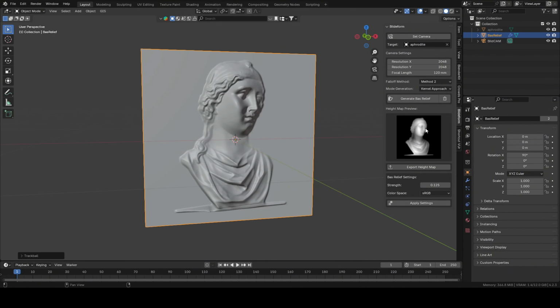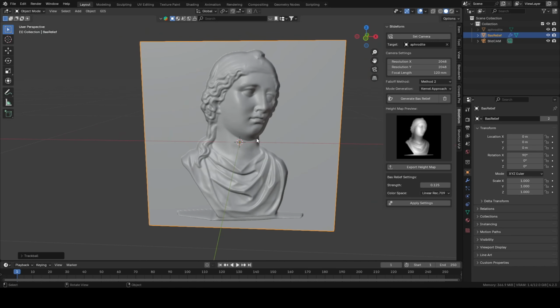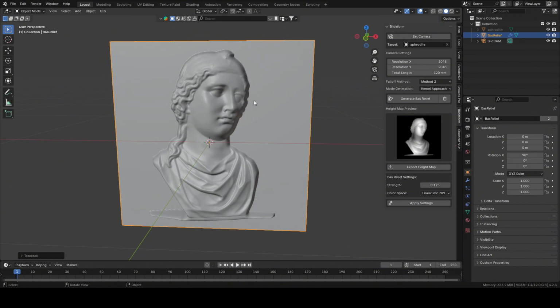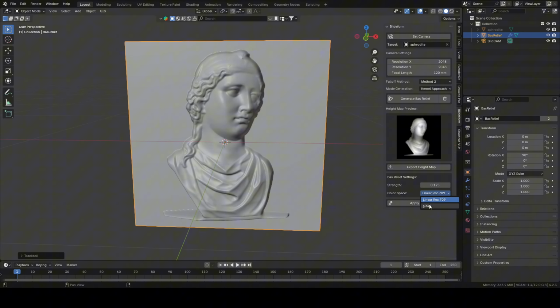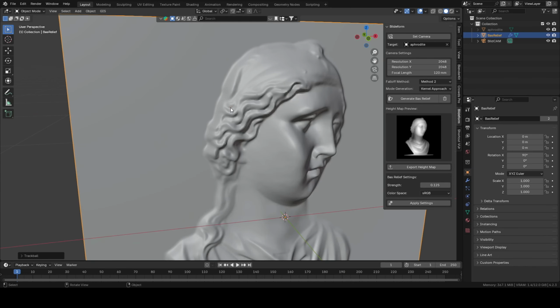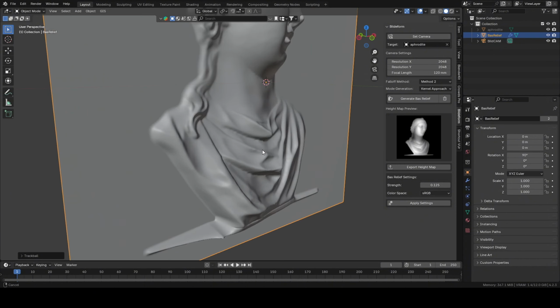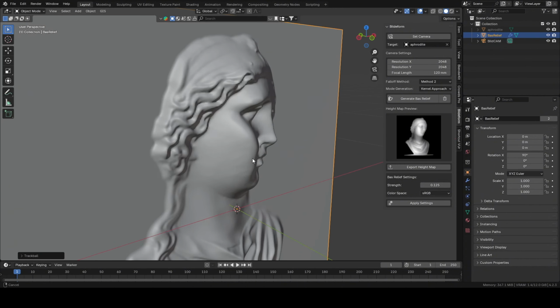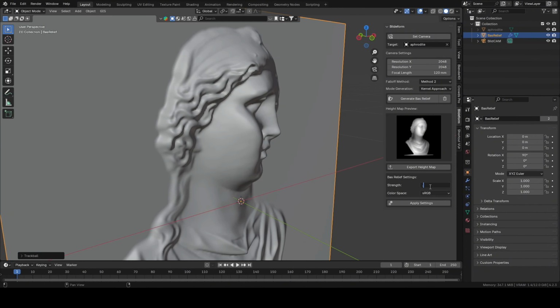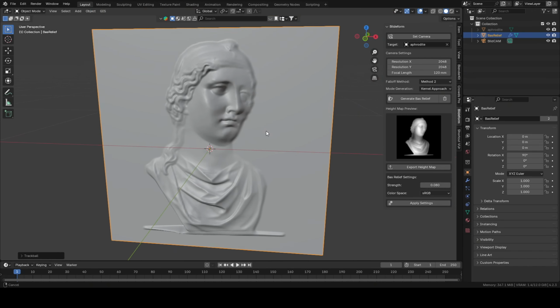Here, we can preview between two color spaces. Each one will give us different results. Even so, we have a much better result that we will not get by the conventional method, as I show in the following image. I will change the color space to RGB, and as we can see, it generates a bas relief with a more natural geometry and a more uniform displacement with the plane. In this case, we can adjust the distance to our liking to see different types of results, and be able to see if we like it or want to change the rotation.